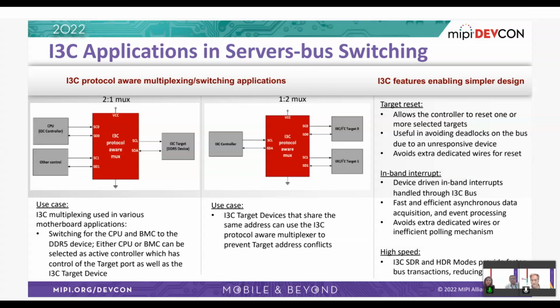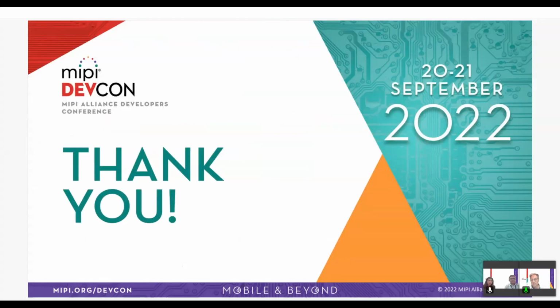Okay, clear. Thanks. I suggest we have the last question. How does I3C standardize bus management versus I2C? I2C has a number of bus management features. Yes, I2C primarily defines the physical layer and some of the higher layer functions, but pretty much every manufacturer or every device in the market uses some different form of it. For example, how to start a conversion or whether to add a CRC to it.